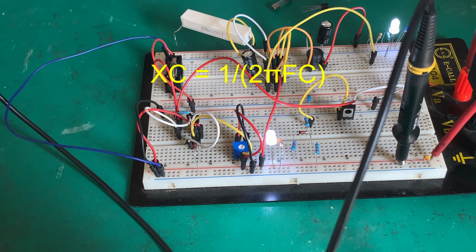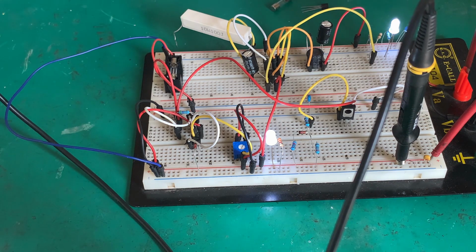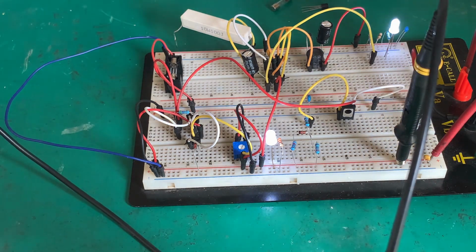So we took the frequency of that noise that was happening on the base, which was roughly about 9.5 megahertz, times 2 times pi times 100 nanofarad. Take the reciprocal of that, you'll find that it's a couple of milliohms resistance.